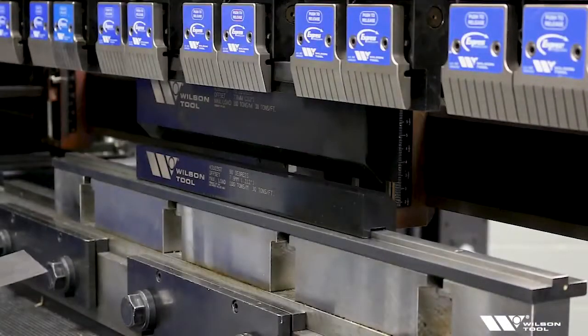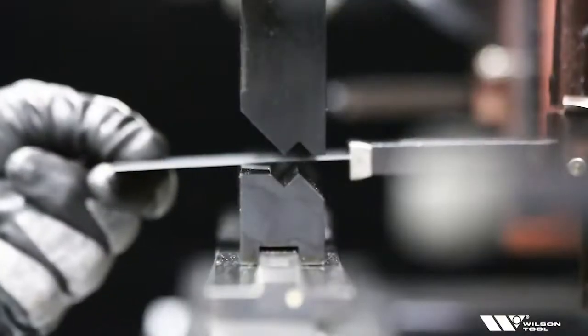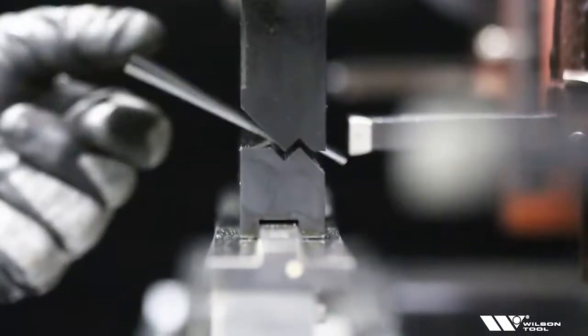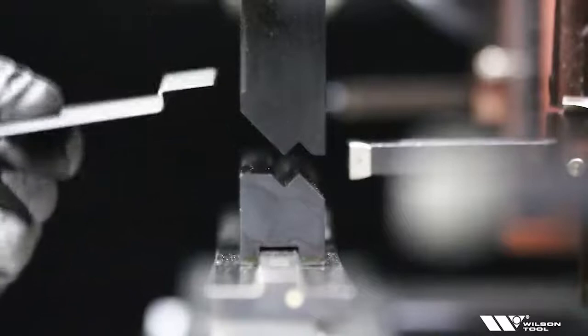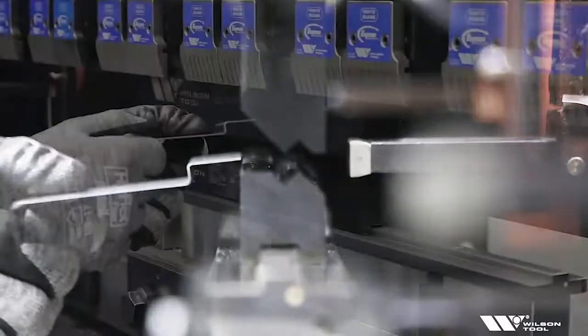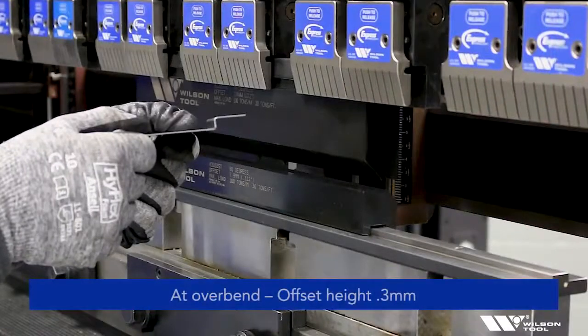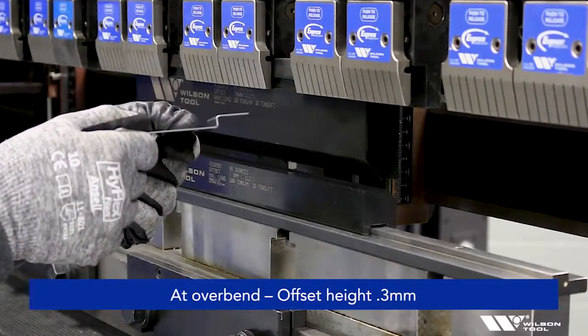So I've got 4 different bends that I'm going to make for you here. And the first one, we're actually going to overstroke a little bit. We're going to come down and create a little bit of tonnage. And when we create that tonnage, something we didn't talk about, but you can actually overbend. So if you can see, this bend is actually past 90. What it did is we hit the 90-degree included angle and it sprung in.